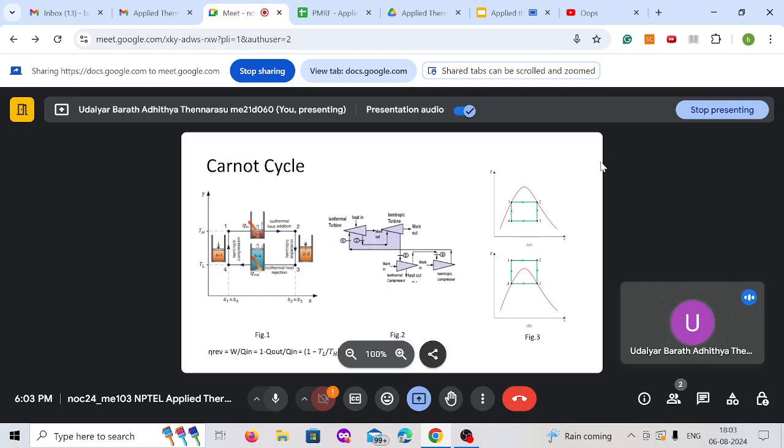So you have a very small fraction of a second, and in that time there is hardly any heat transfer. There is very little time for heat transfer, so that is an isentropic process. That is why we assume most of the expansion and compression processes here are reversible adiabatic, because the process itself is very fast. So the Carnot cycle has 2 isentropic processes.